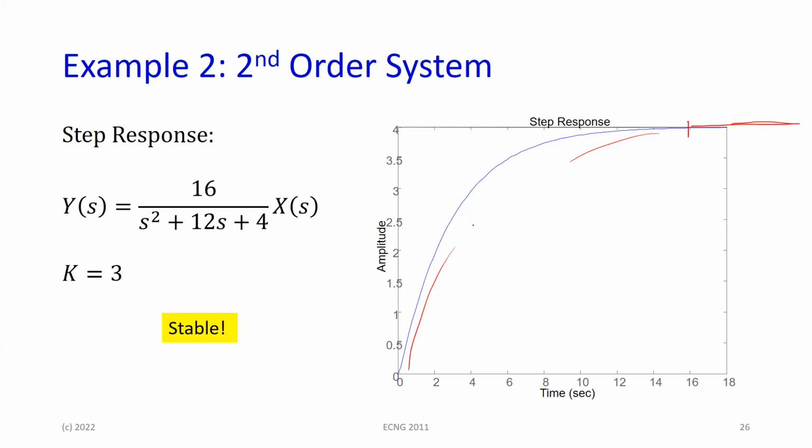Remember, and this is a little revision, if you wanted to find what is happening here and what is happening here, you have the initial value theorem, IVT, and you have the final value theorem that could tell you what the steady state response is going to be, right? So you could run that here, even before you plot it, to see what the steady state response is going to look like.